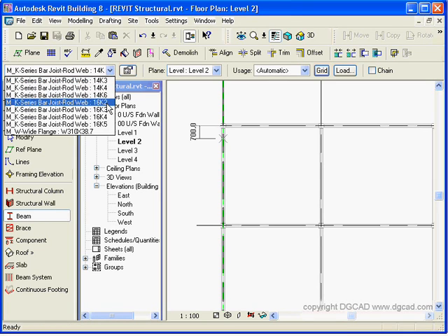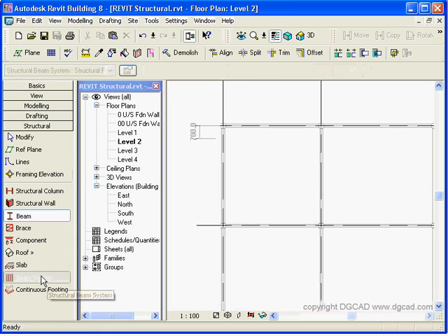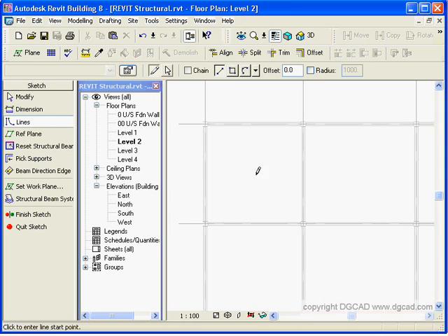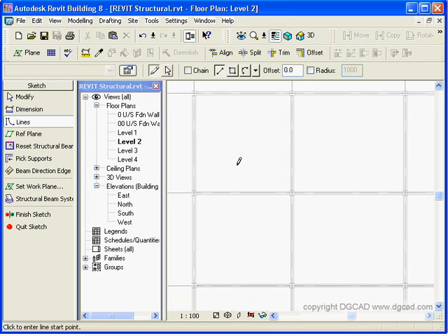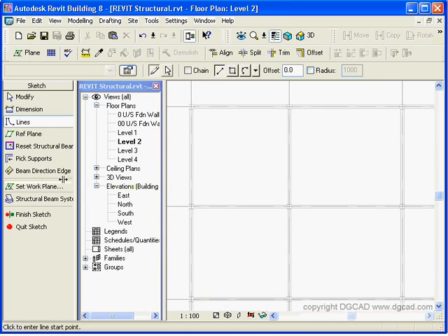So we can say, okay, we're going to pick one of these joists right in here, and I'm actually going to hit beam system. Okay, beam system. If I want to draw one joist, I could draw. We'll mix this up a little bit, but I'm going to start by saying beam system, and I'm going to create a little area in here. And if I wanted to, I could actually have the joist go across here as well, or right down to there. Depends on the bounding area.